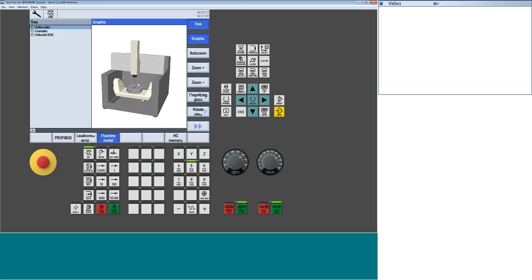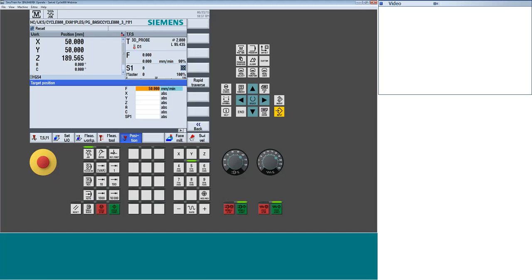Now from there, once I start to get my head around it, how do I start to manipulate where this rotary is? Well, one of the simplest, most basic things would be just to do an angular offset. So if I was to say, I want to set my A at a 30-degree angle, we'll do negative 30, right? So maybe this location here is where I want an initial 0 staged. Maybe I don't, for some reason, want it clocked.